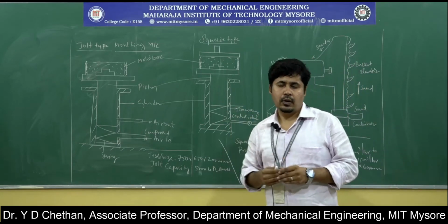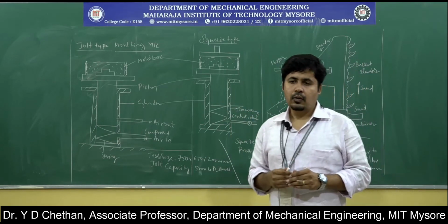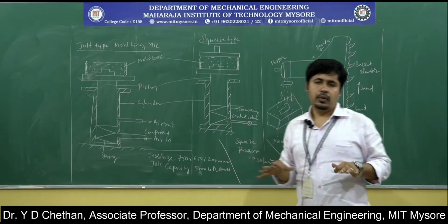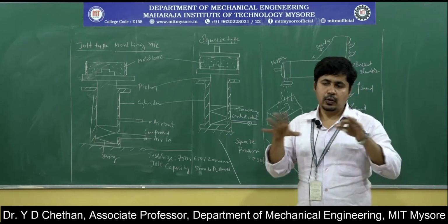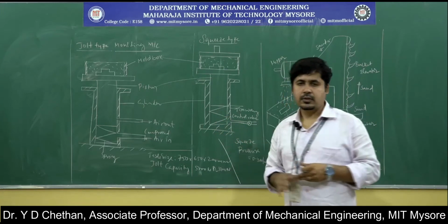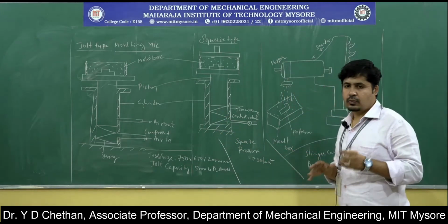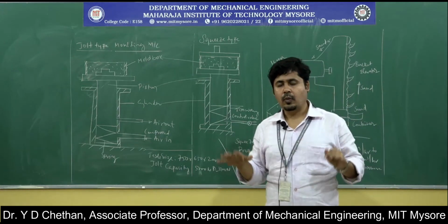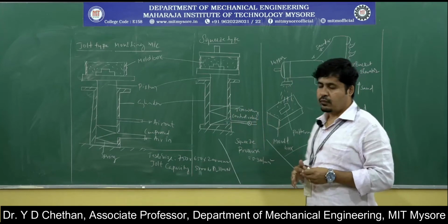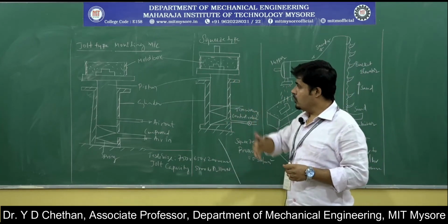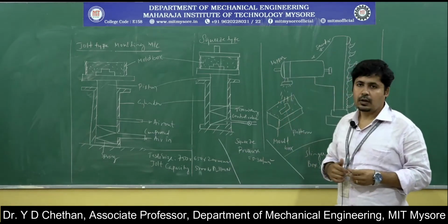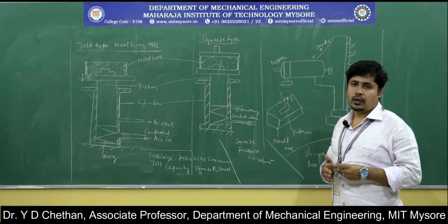These are all the different varieties of molding techniques, where we were using hand tools to ram the ingredients into the pattern to get the desired shape and to get the casting process done. So here, in order to have uniformity in the compaction of the sand and a faster rate of molding, we can eliminate the hand mold tools and human intervention. We are considering machines called molding machines.